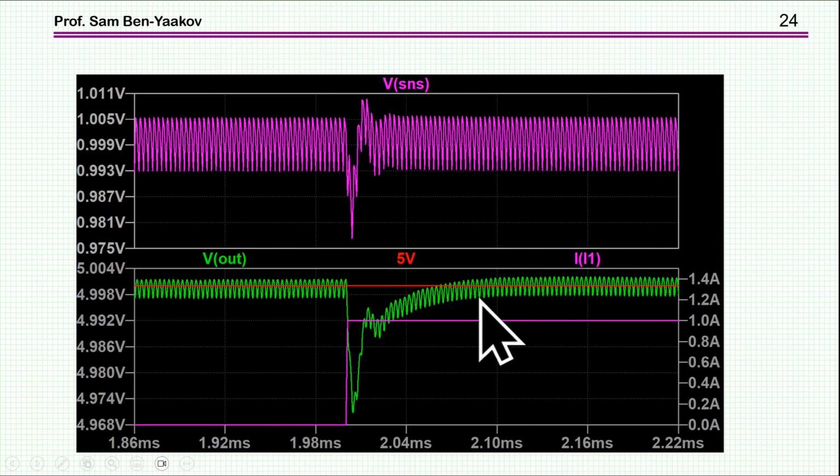And here we have a nice DC control, it's 5 volts. And also we have a capacitor with a low resistance, low ESR. There is very little ripple at the output. You see here the ripple at the output. So this is a very nice concept for design. And indeed, there are commercial controllers which are designed according to these ideas.